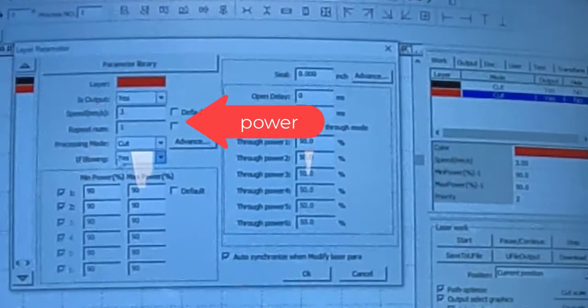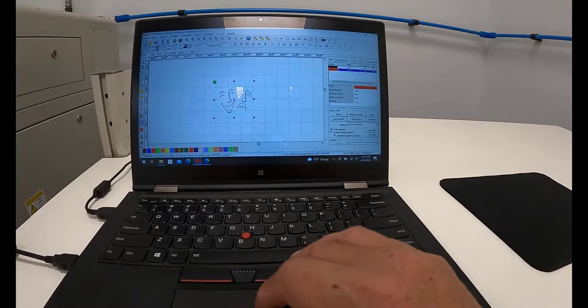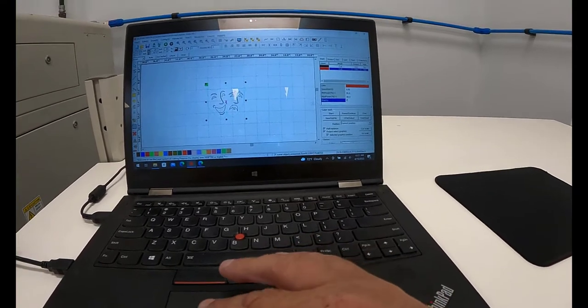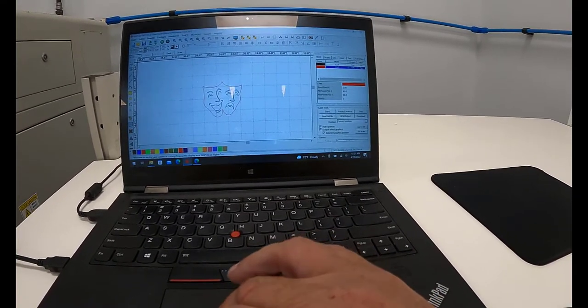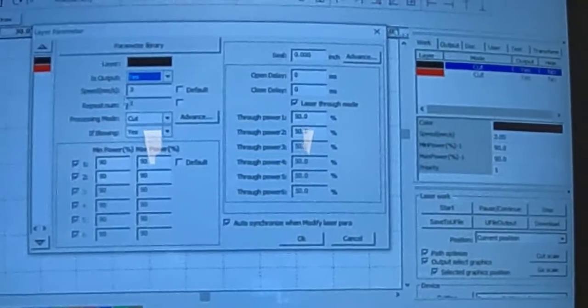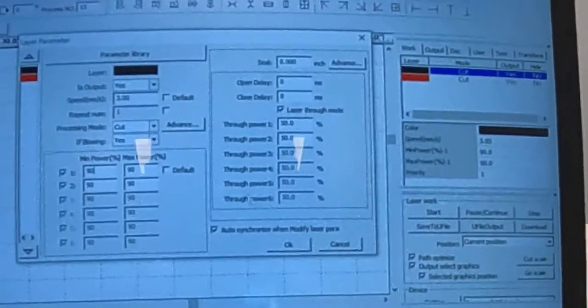Based on which laser cutter we're using, and if we're doing a through cut or an edge cut, we select the power and the speed, because the power and speed determine if it's a clean cut through or a partial cut through. For acrylic, we're looking at a speed of 3, a power of 90 to do a clean cut through.